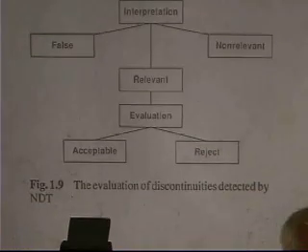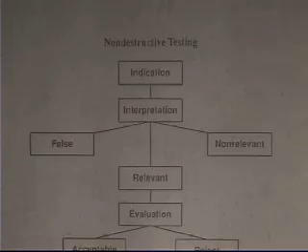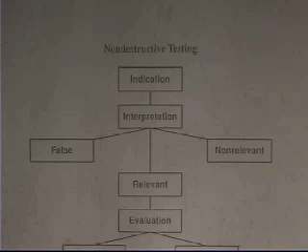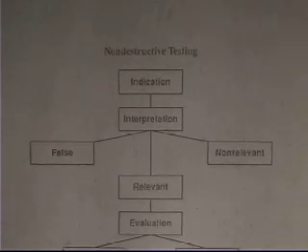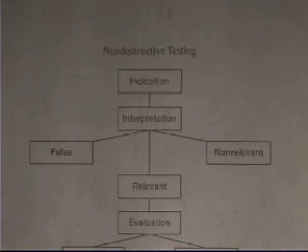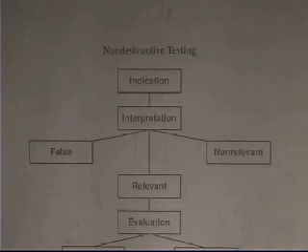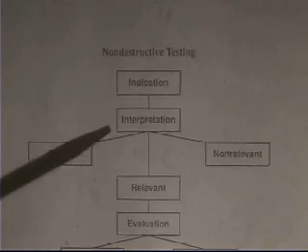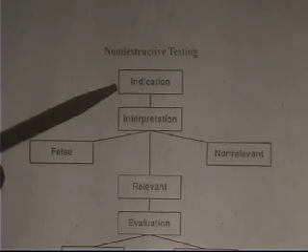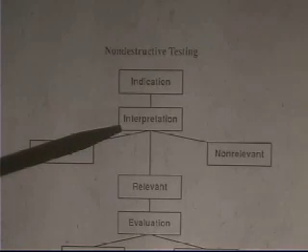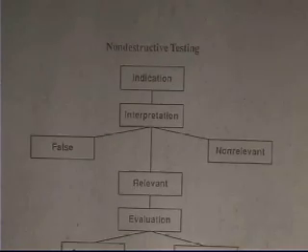Okay, you did a test, and the test came back and gave you an indication. An indication certainly doesn't mean it's a defect yet, even if it is a flaw, but an indication is not necessarily even a flaw. There may not be anything in the material, but this may have to do with some artifact of your measurement technique, rather than a true flaw in the material. Well, if you got an indication, that's your non-destructive test. Your non-destructive evaluation involves some interpretation.